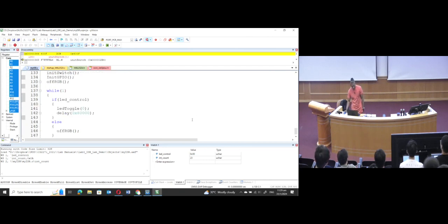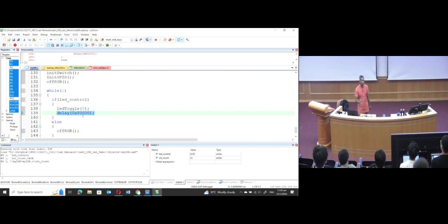The way I just hack around the bounce effect is to put a delay first. When I first register the interrupt and do the toggle, I come back to the main loop, correct? And then I just delay myself some random value until I come out of it. Again, this is not an ideal solution, but it's an easy hack just to get past the mechanical bounce.